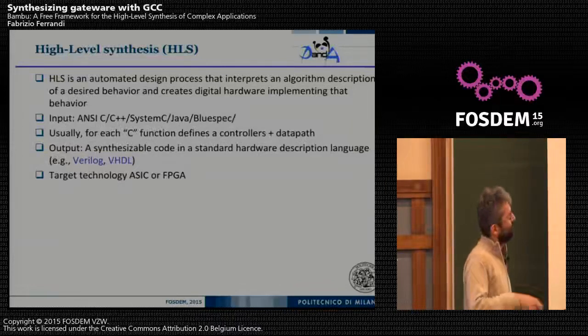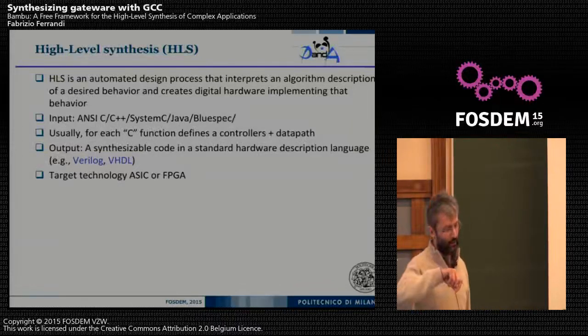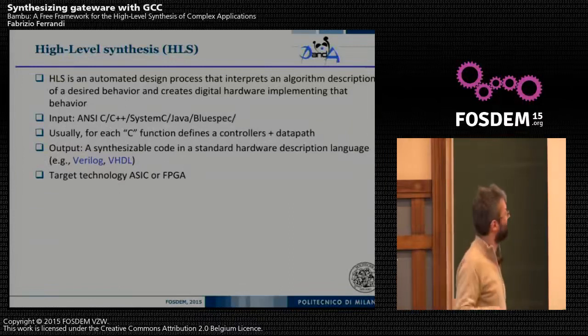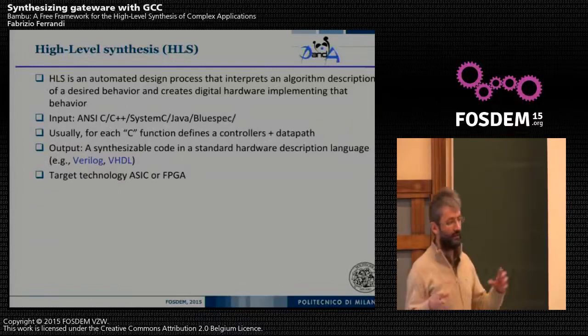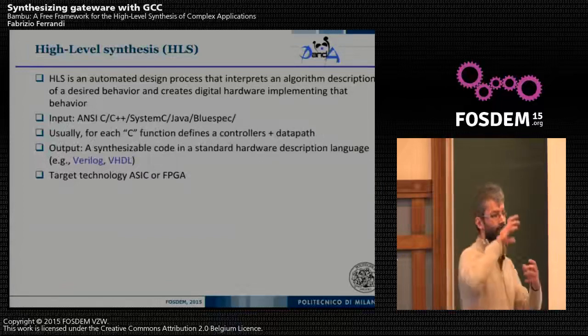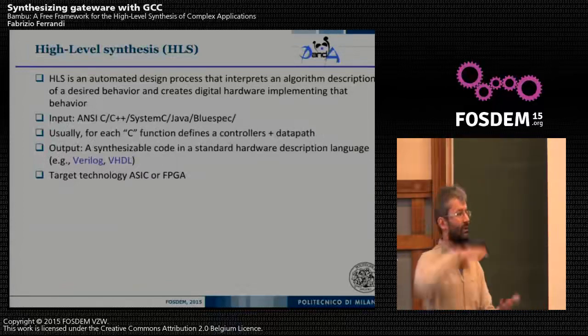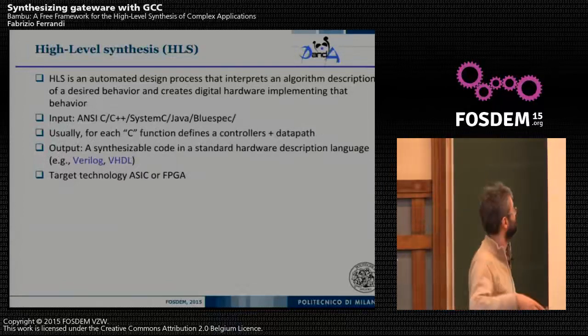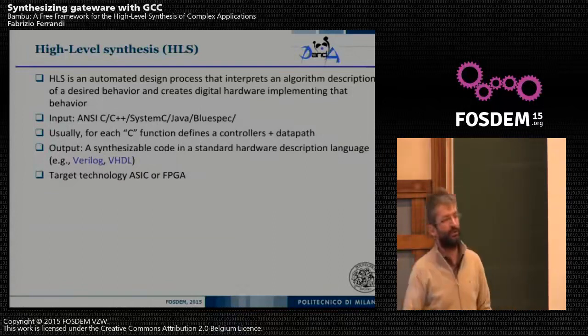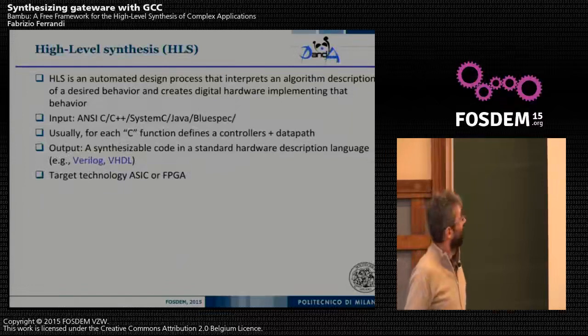The idea is to generate, for each function you have in your description, a controller and a data path in hardware. So you have the controller and the elaboration unit described in RTL at the end of the process. That description should be synthesizable Verilog or VHDL.